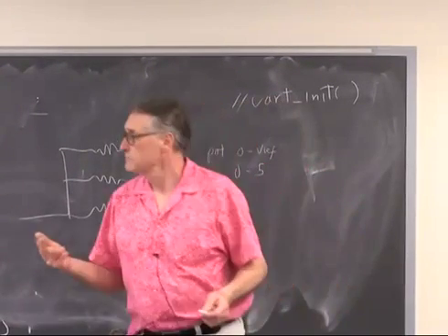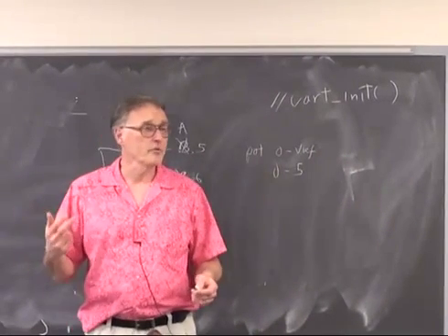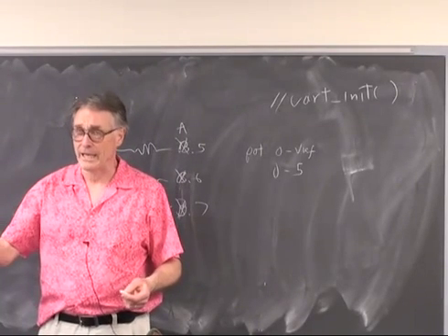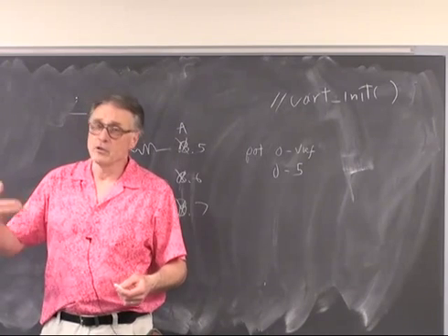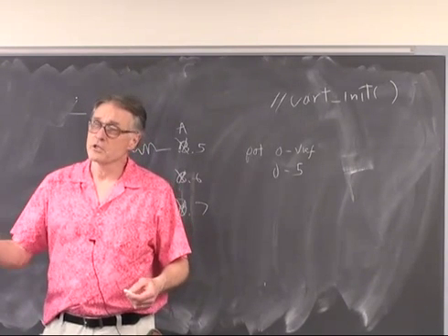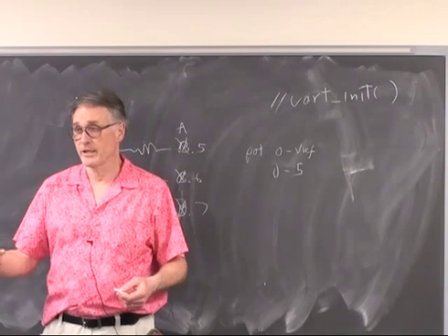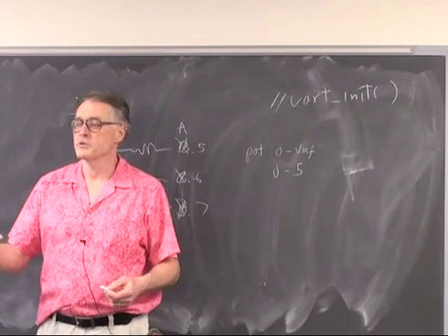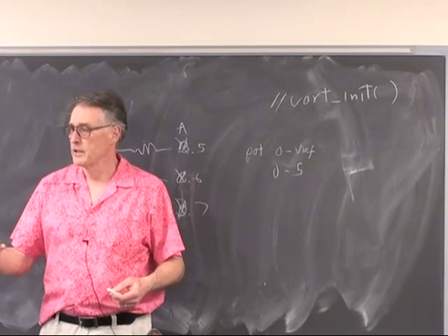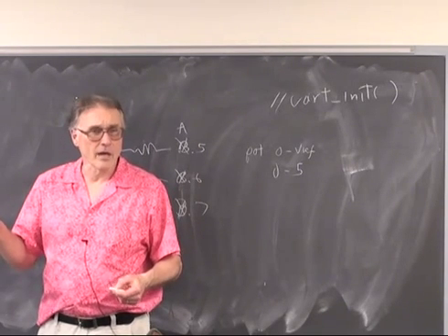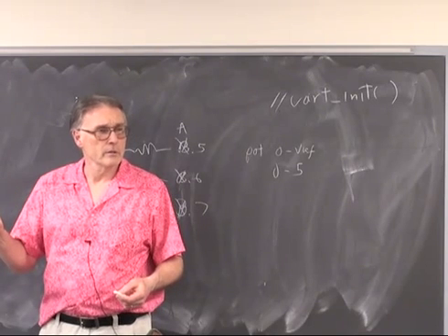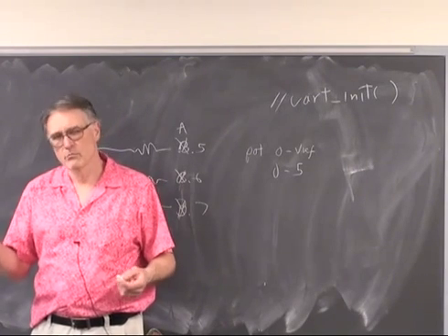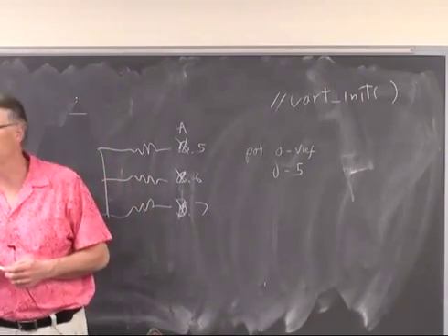Oh, printing floating point. I put the directions for include. There's a library you have to link in, which is not included by default. I put the instructions for linking it in Lab 1, so that it's in the procedure section of Lab 2, where you can find it easily. There's one line you have to add to the linker options in order to print floating point. Otherwise, you have to do the floating point conversion yourself. Boring. Any questions about Lab 2?